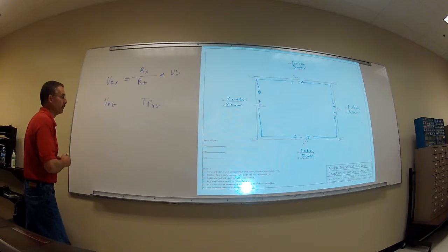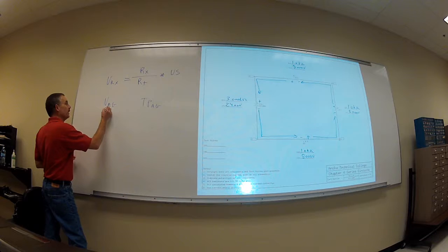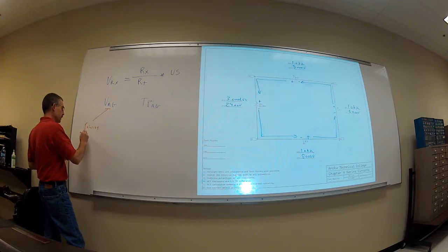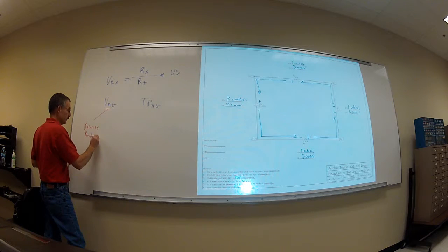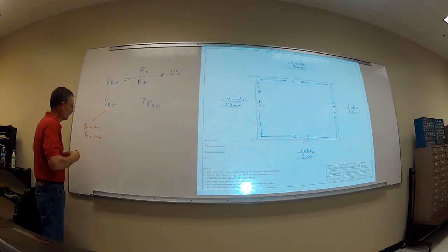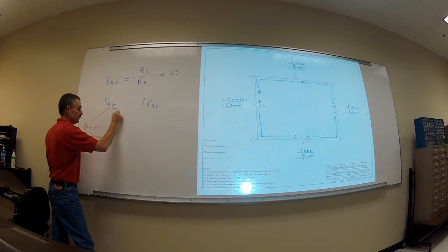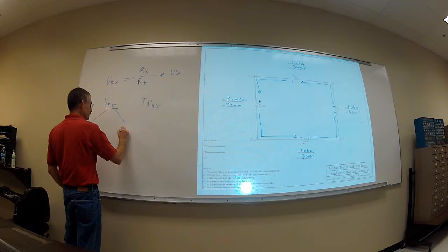when we're looking at our test point voltages, we've got 2 letters here. One's going to represent what our polarity is. This is going to be always our red lead of our meter. The second letter always represents the point of reference.